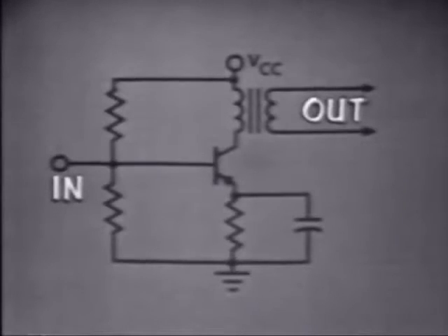In the LC circuit, we found that frequency is determined by L and C in the tank. Now, the same thing is true in the amplifier that oscillates. But since there is no frequency determining device, the frequency of oscillations is determined by distributed L and C. That is, the input capacitance of the amplifier, the inductance of the leads, or any inductors and capacitors in the circuit. Very difficult to predict the frequency.